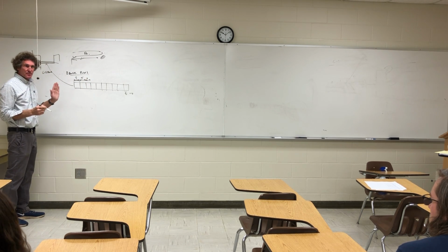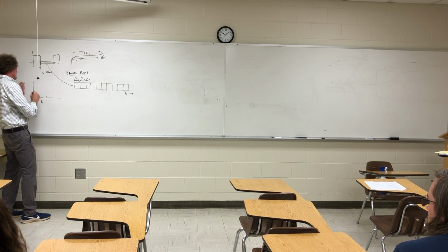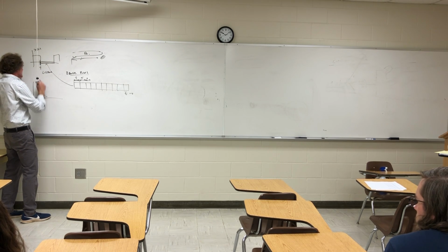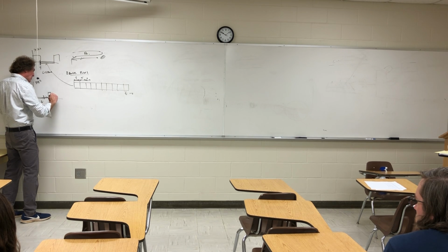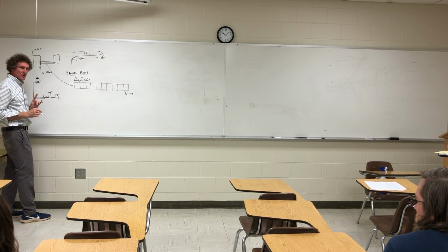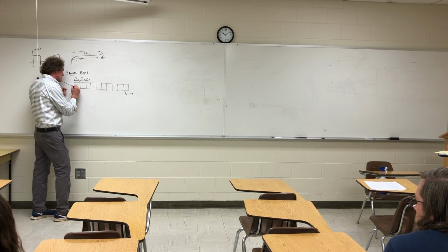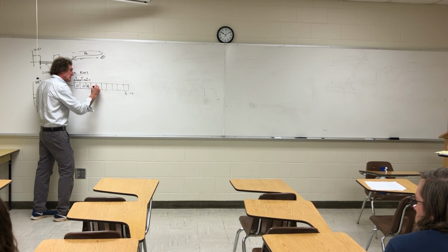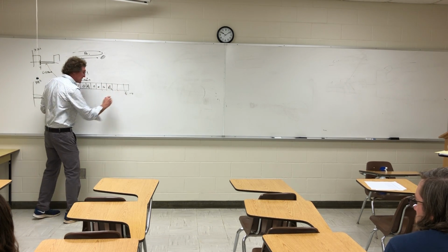What happens is this. When I'm listening, we get this signal, but this is versus time, this is x of t to transmit, and this is y of t to receive. I'm going to have a delay to here, and then I'm listening. And then all of a sudden, at some point, I'm effectively going to get something like this. I'm taking all the noise out, but I'm going to get targets that are noticeable, something where I can say, yes, it's above a noise threshold, I've got targets. So there's none there, then I have a target. A target has an amplitude A1. Then none, another target, amplitude A2. Y'all follow me on this? These are the range bins here.